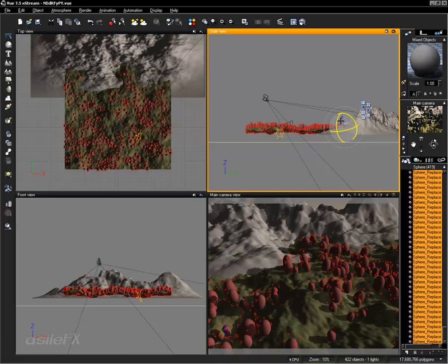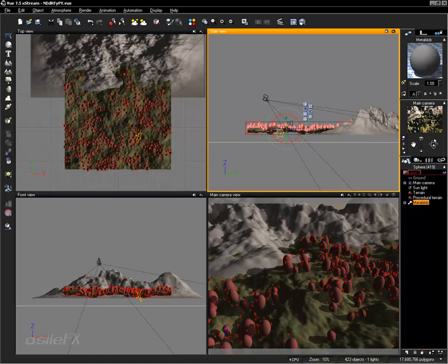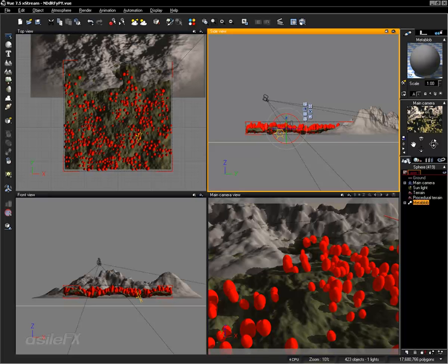Okay, and now for the part that is going to combine all this together. Now we can either keep these as they are, converting and baking them to polygons, but if you want to work on something in a little bit of a larger section, what we can do is create a metablob. Go over here on the left, select Create Metablob Object. It's going to fuse all these together, and it's just like metaballs or any of the similar technologies where it kind of adaptively subdivides a skin around a bunch of given objects.